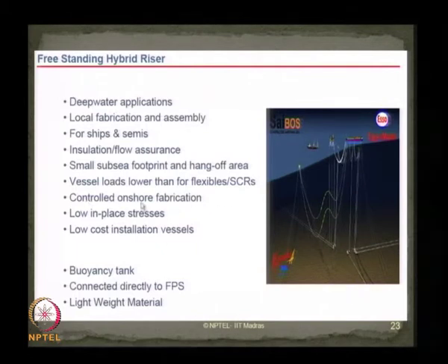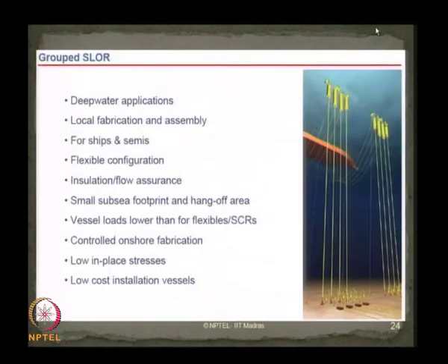They also have controlled onshore fabrication and low in-place stresses, which has been measured by analytical studies by different researchers. It has also been seen that low cost installation vessels are required for commissioning these kinds of risers in deep waters. They are useful for supporting systems like buoyancy tanks. They are connected to the FPS directly and they use generally lightweight material, therefore the installation becomes simple and easy because they have tower supporting systems which are used for installing these kinds of risers.